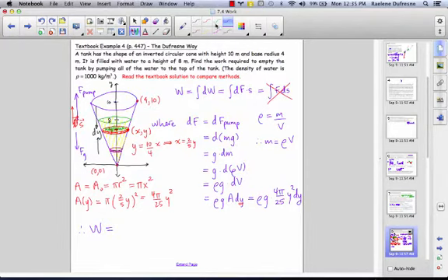Unfortunately, we're not done because that expression is just this expression. We still need to come up with s, the displacement. Well, the displacement is purely vertical to take that slice to the top, and we're going from a beginning position for the typical slice of a vertical position called y to a vertical position called 10. So when we want to calculate the displacement, it is y final minus y initial, and we have 10 minus y for the displacement.